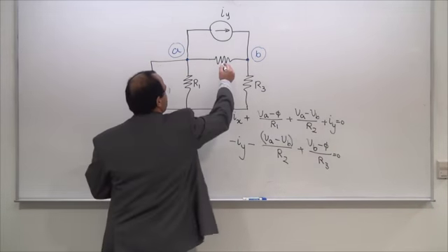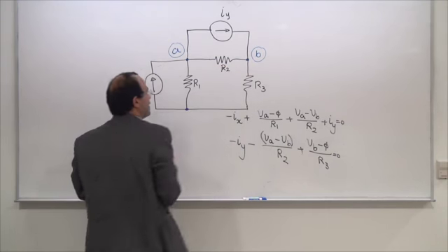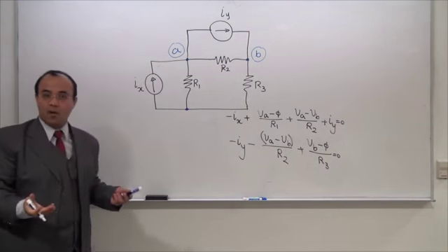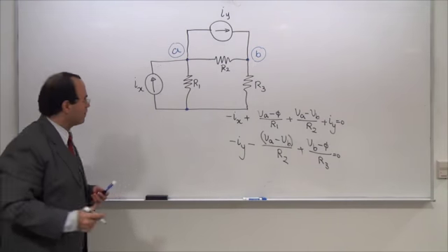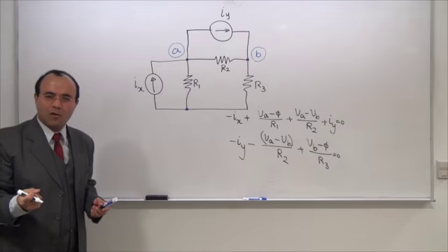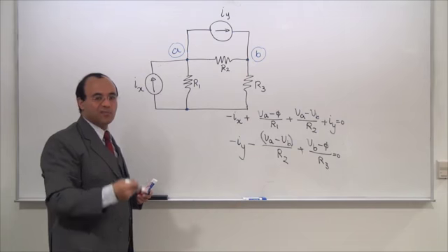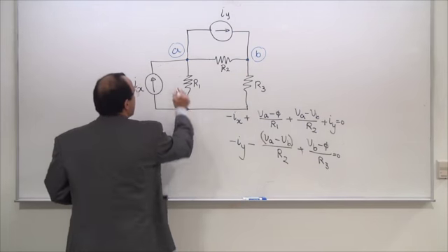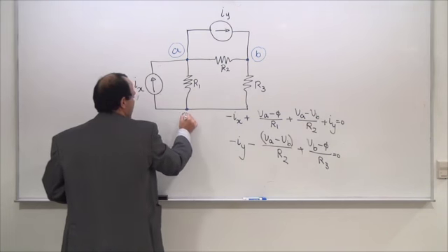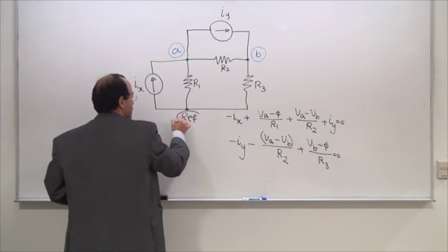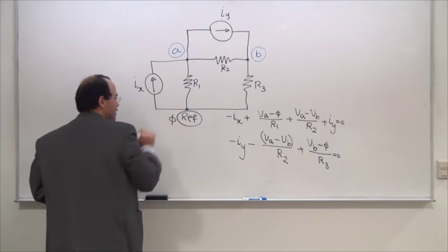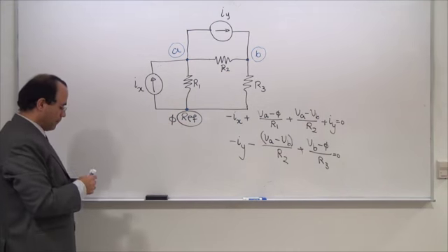You have a design. In this design, you have a number of components, a number of nodes, a number of loops. You need to identify the number of nodes. You have A, B, C. This is nodal analysis. It's nodes we need to identify. So you have A, B, and then you have a reference node. This reference node has a 0 voltage in mind.